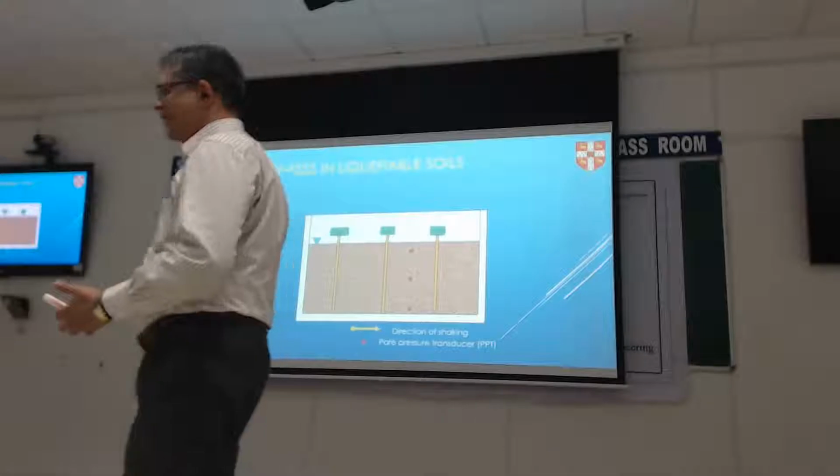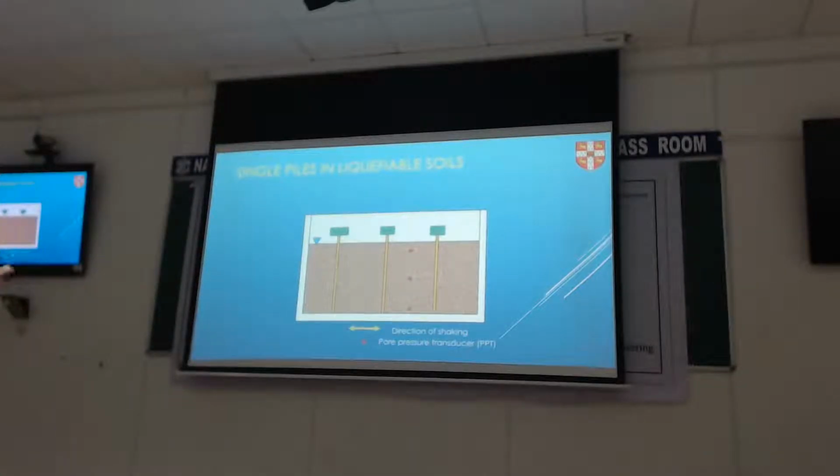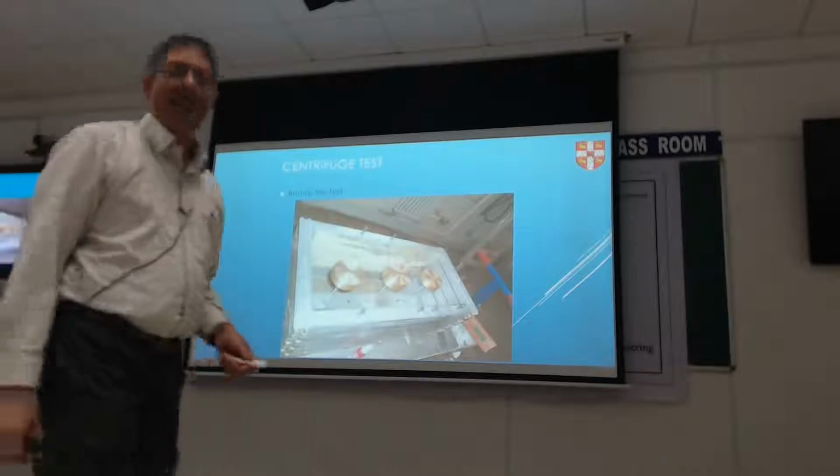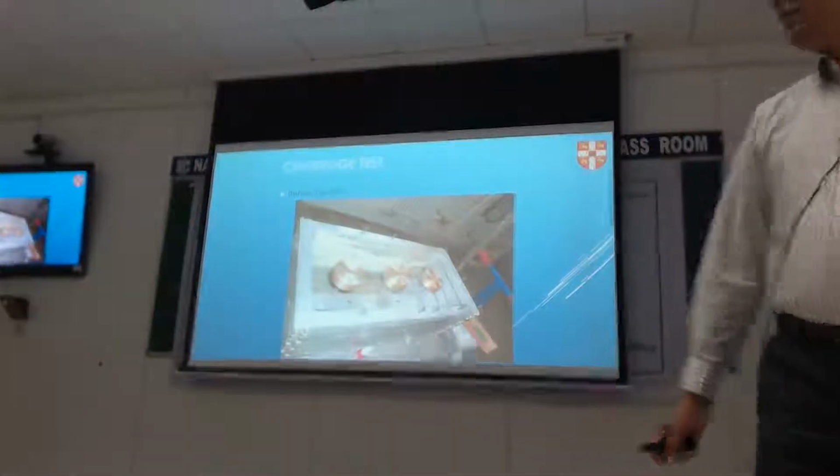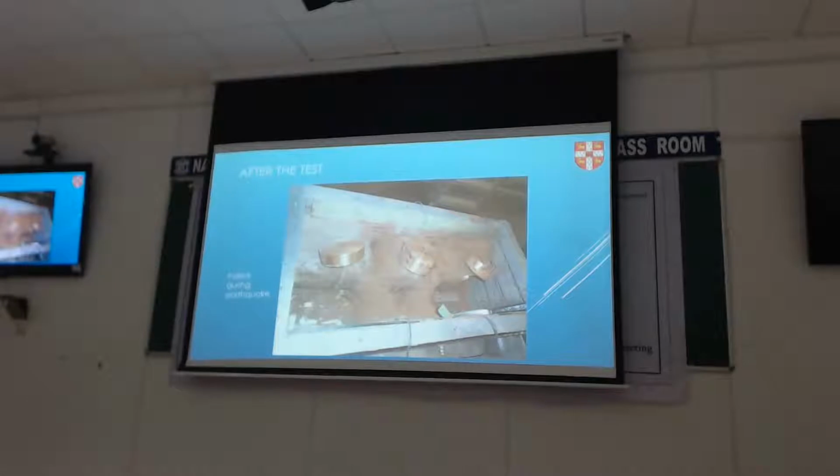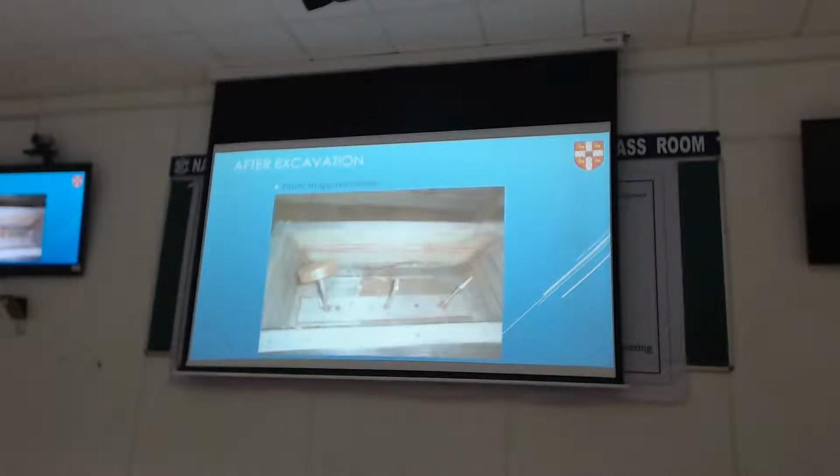All we needed was loose sand and a centrifuge and a shaker. So he got himself these loads made, which are obviously brass loads on aluminum pipes, and then he filled them with sand. I'm showing you post-test behavior, and this is what happened to them. So they all buckled, as you are excavating. This is after the test. Got some more pictures. Some actually lost their heads as well. Some were still hanging on to the loading cap.